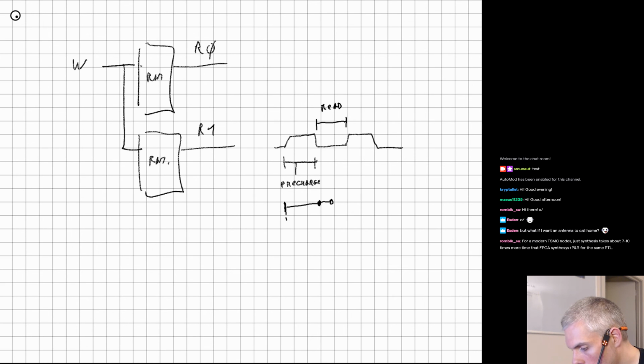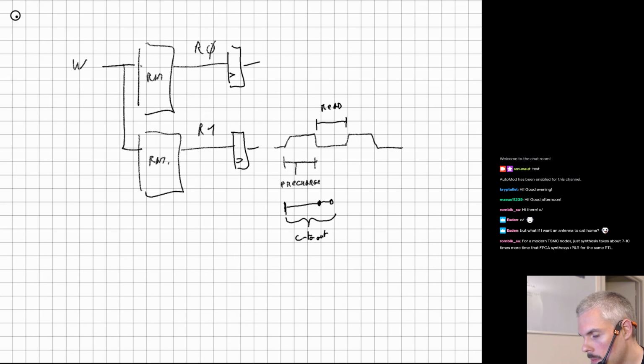And that meant that the total clock to out of that macro was actually rather large, which is not necessarily ideal for a register file, because that means you have a 2-cycle latency for your read, since you'd have to put a register here again. That adds one pipelining level, which, if you have a pipeline flush because of a missed branch or something, is one more cycle of latency. So that's the other reason that made me think that using OpenRAM for a register file might not be ideal.